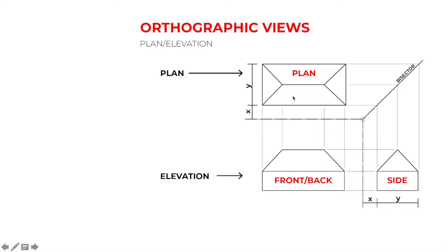So it's really nice to be able to, whatever the figure is, whether it's an object, a building, or some other construct, construct them all on one page. And you can do so by using your T-square or parallel glider to match these different measurements so that things start to line up. And then you can see how this bisector here, you carry over the dimensions of the plan to the bisector, you can bring it down and actually match the top ridge line to here and then the far wall to there. Everything remains consistent in terms of its length.